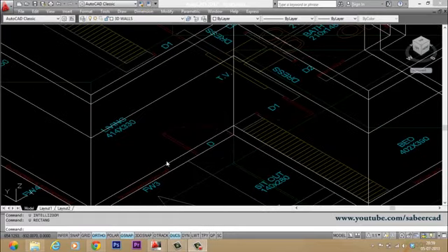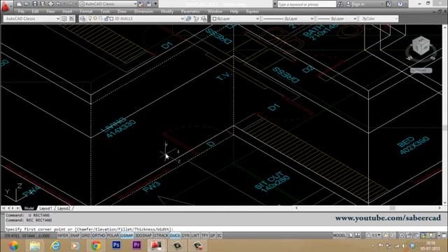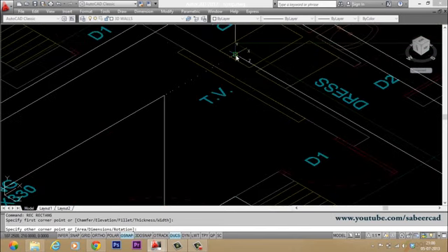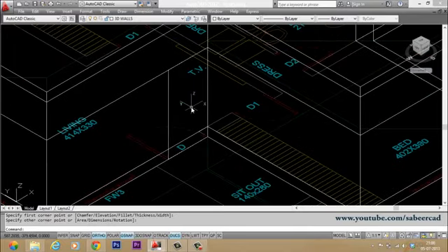Now let's move on to the door. I'll make a rectangle which has got the size of the door. So I gave rectangle command and I want the door to align with this face. So I'll take the cursor onto this face and that face got highlighted. I'll click one corner here and the opposite corner is going to be here because this is 1 meter, which is the width of the door, and the height goes up till lintel. So you have a point here, so you can just click there. Now you have made the profile for the door.